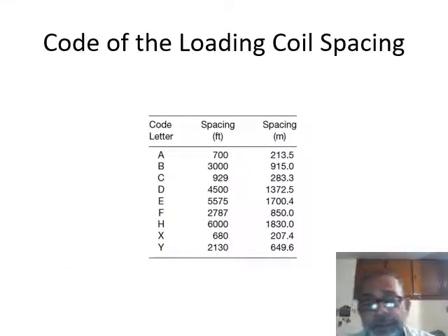Now, there is a particular standard about these loading coils, and they have a code letter. For example, if it is code letter A, it means that such a coil would be placed 700 feet apart.